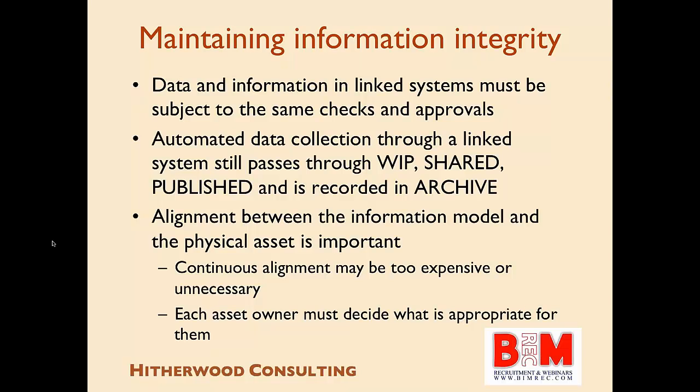It's up to the organization that's running this process whether they really need their information model to be in continuous alignment with the physical state of the asset, because that might be a very expensive solution. So real-time measurement, lots of automated sensing and processing. It may be that the most cost-effective way of aligning the model and the asset is actually to do a periodic update, maybe every few weeks or every couple of months. Again, that will depend on the nature of the owner's business, how crucial and critical that asset is to particular parts of their organizational operation. So again, the PAS allows for either of those routes to be put in place depending upon what the organization thinks is best for them.